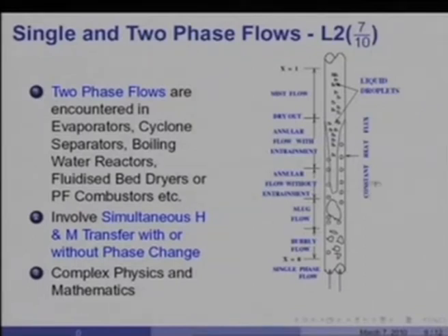Heat flux is falling on the surface. As a result, first nucleation sites would be established when the temperature of the wall increases, and small bubbles of vapor would begin to form, and they would penetrate inwards into the core of the flow.